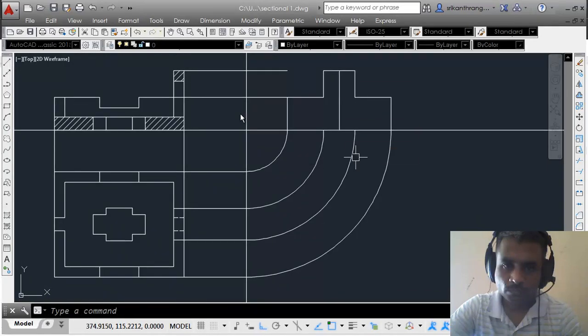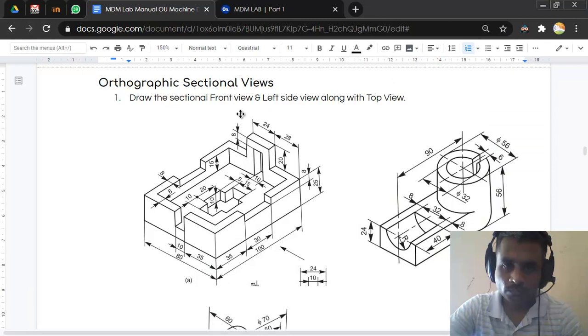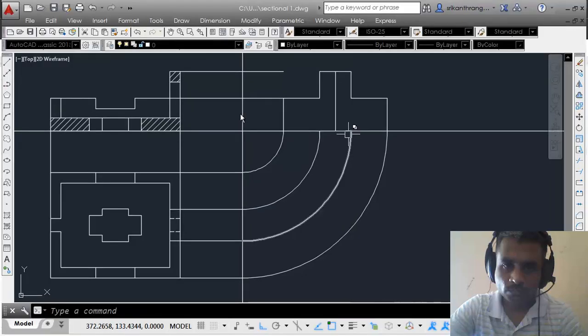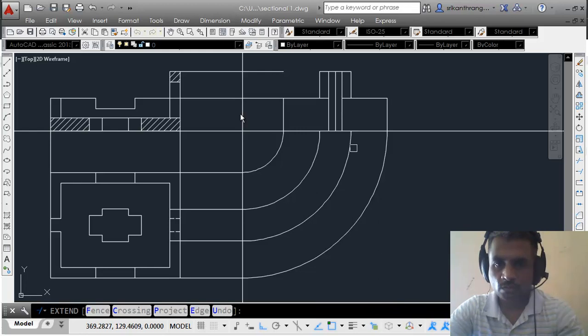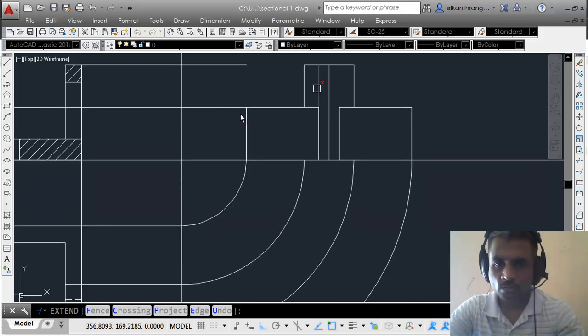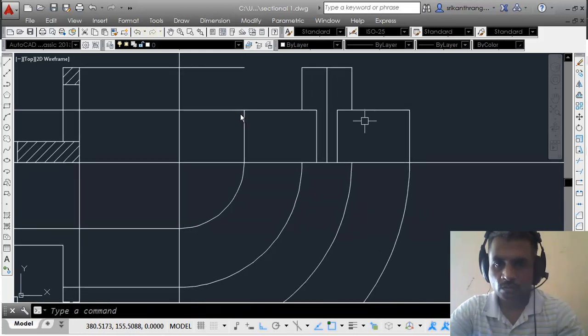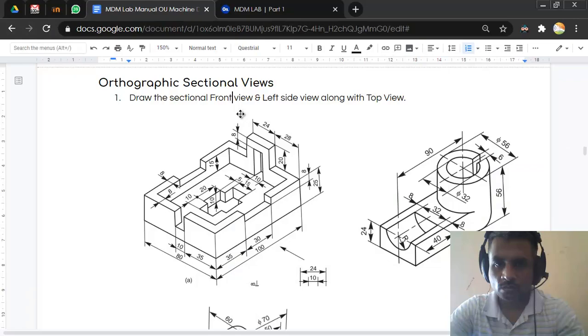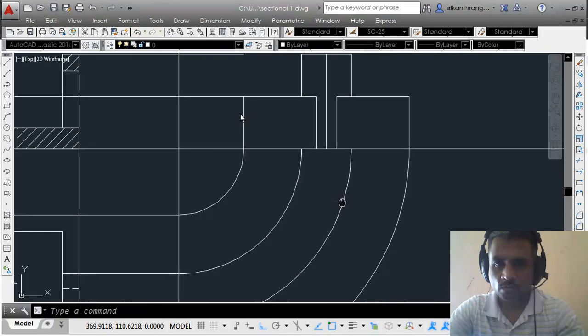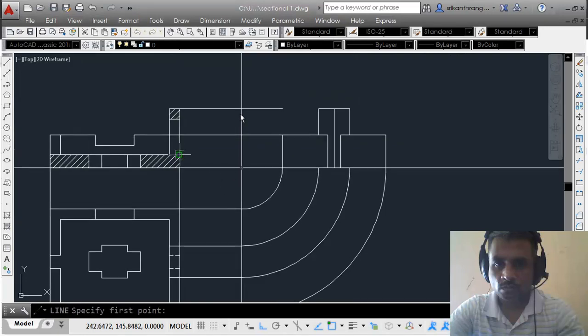Now there's going to be the height displacement of 10, offset 10, or I can take this as a reference from front view. It's going to be perpendicular. Then I'm going to trim it off, and then I'll just break this and this side. Okay. So these lines are different. These lines are going to be hidden. These lines are going to be hidden. So I'll just change their properties